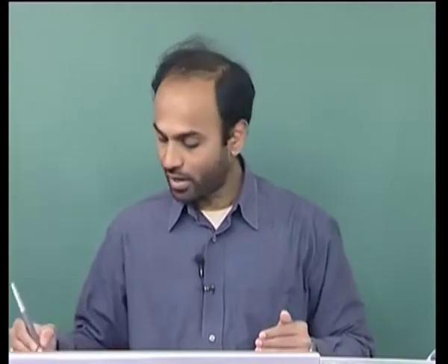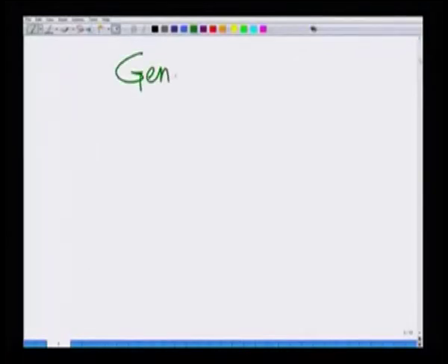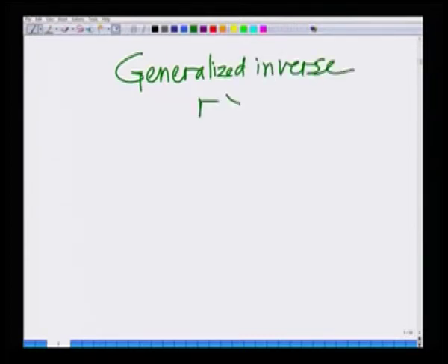Second, even if R equals T, that is, I have 2 receive antennas and 2 transmit antennas, I cannot always guarantee the existence of an inverse, because if the matrix does not have full rank, then it is not invertible. So because of these problems, we move on to a slightly more refined definition of an inverse. I will specifically consider the case when R is greater than or equal to T and define a generalized inverse, for R greater than or equal to T.